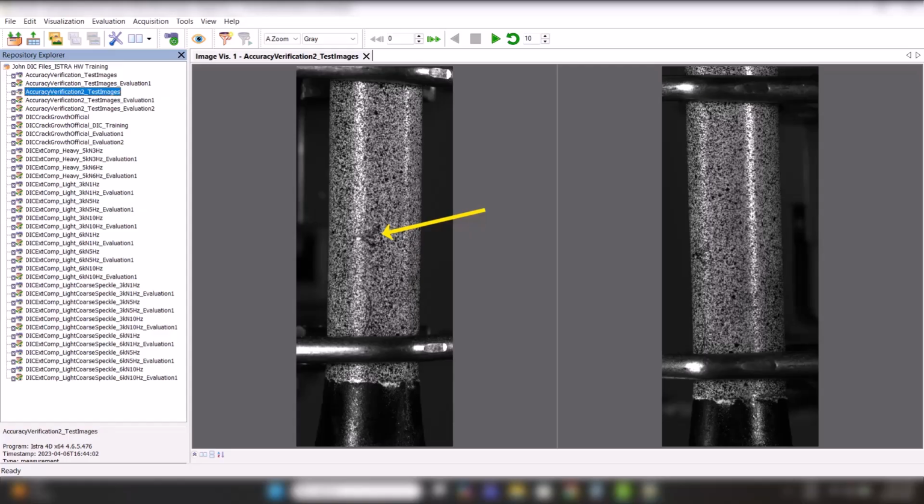So then the optimum focus distance in that case is biased towards the front tangent plane of the specimen. And that might not be what you want, right? You might want the optimum focus distance to be a plane that's going through the central axis of the dog bone. One way to accomplish this is to first perform the focusing process using a flat specimen or a flat target located at approximately the center depth of the eventual cylindrical specimen geometry, and then afterward install the cylindrical specimens into the grips.